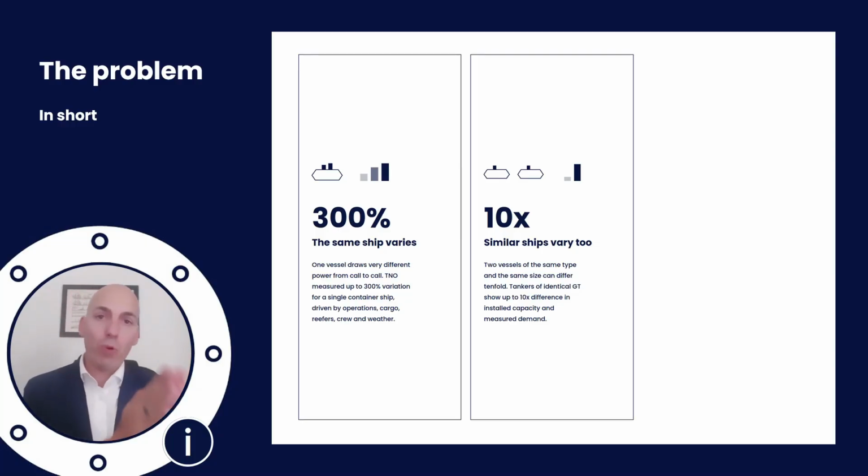So within the same range of ships, you can have a tanker Panamax that's intended for just loading on, offloading, typical cargo, no cooling or heating functions. Or you can have similar sized ships that have a lot more functionality, need to do stuff on board, have a lot more energy need than those others. And if you have to accommodate both at berth, then making estimates on the power demand and the equipment you need is a big problem.